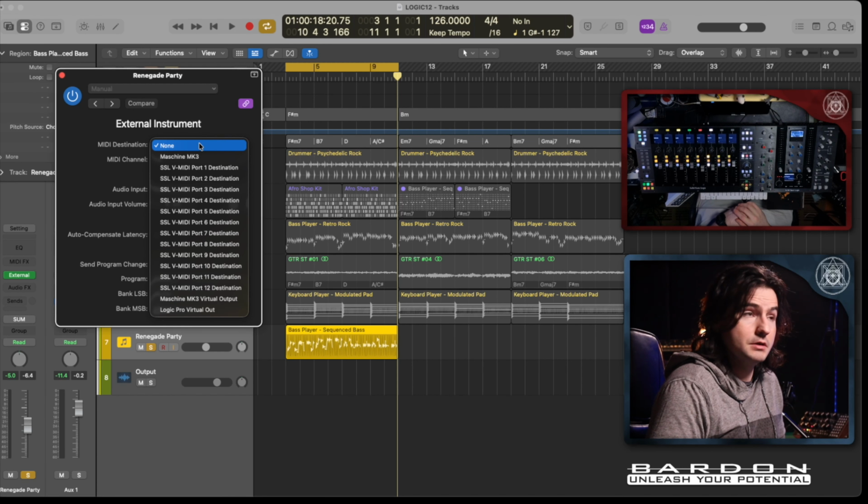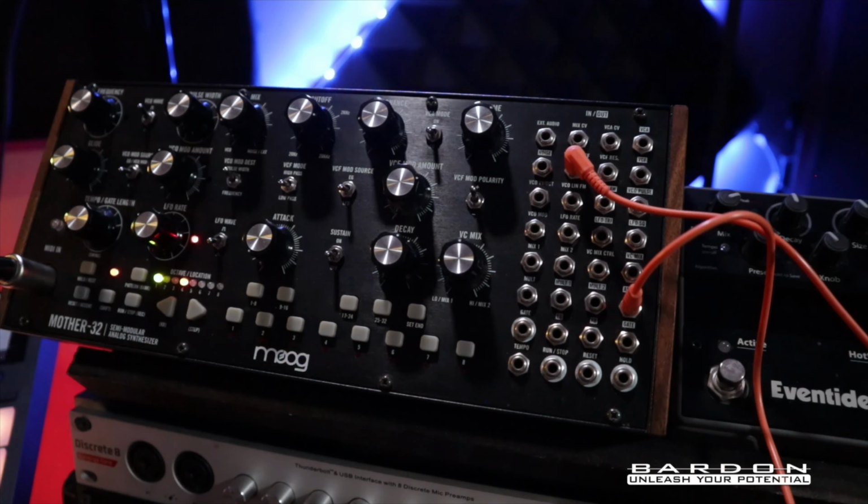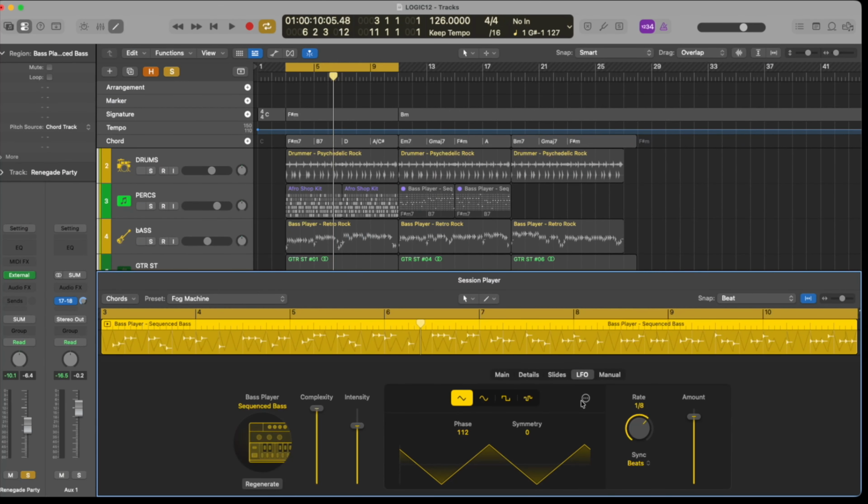Of course, nothing happened. Why is that? Easy. I need to assign the output of this LFO over here on Logic to a CC command, a number, that is going to be understood by my Moog, getting into the Moog through MIDI, so it can route it to the assigned output. So how to do that? The Moog expects signal and allows you to route signal coming from channel 1, 3, 4, and 7, if I recall correctly.